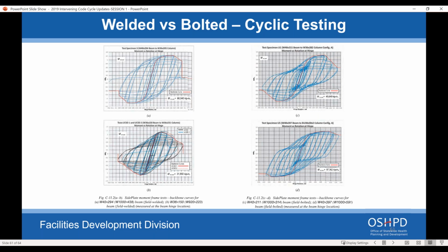While the bolted connection can show plastic deformations exceeding those of a welded connection, you can see there's some slip midway in the moment capacity, and then it picks up strength after that to reach the full moment capacity of the beam. That's how they're able to get further out on the plastic rotation curve.